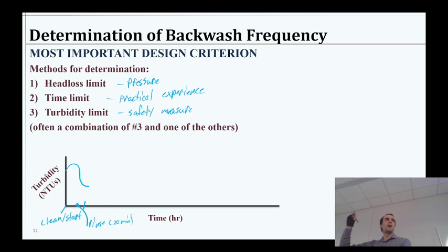be a lot of particles come out because we just disturbed everything. We rinsed as much as we could out, and there's still some stuck there. So there's going to be some that comes through, and the media is just not operating effectively yet. And then we'll slowly operate from there for hours and hours and hours, and eventually we'll probably hit some limit, and we say, okay, well, that's too much.